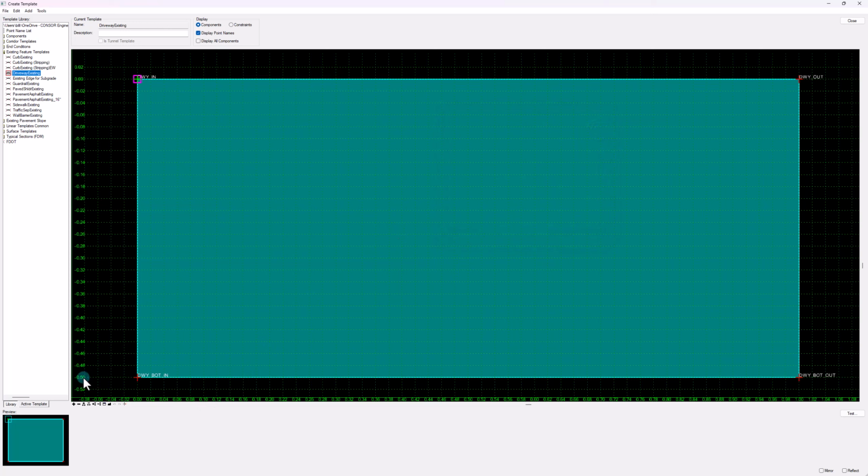You can see how this is 0.5, so it's 6 inches deep. This is definitely supposed to be used for concrete driveways. What I might end up doing is, since I expect that these turnouts are probably similar in pavement design to the shoulder, I'm just going to go ahead and copy this and then paste it here.